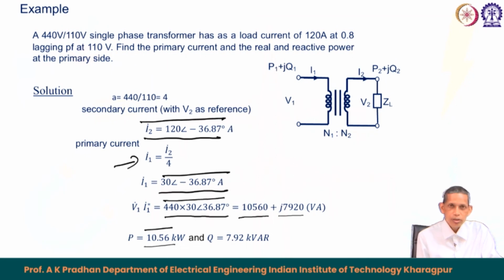So, from this example we see how the corresponding voltages of the primary and secondary coils are mentioned. Based on the load current we can find out the corresponding primary current and then how the corresponding complex power matching happens to be there in the primary and secondary side. So, we say that we have V1 I1 conjugate equals V2 I2 conjugate.